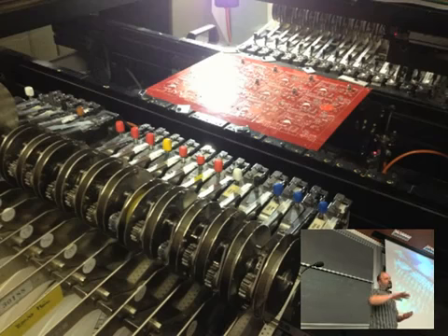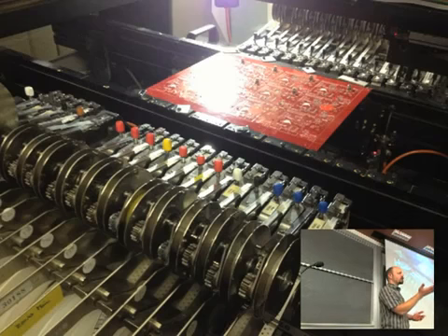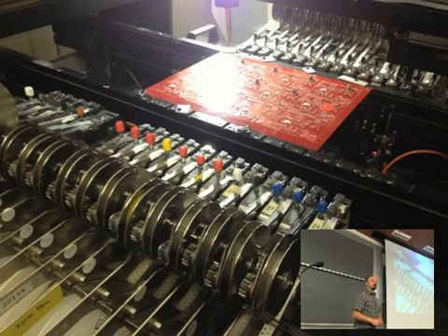Now, of course, if you have 2 layers, it's a whole different story. Because you put the parts on one side, right? If you put them through the oven, great, that will work. But how do you now put stuff on the bottom of your PCB? They actually do that at the same time, and how they do it is with glue. They first put a little bit of glue down, and then put the parts on top of it so the glue will hold them. Then they flip these boards around and stuff the second side, and then shove them through the oven that way. So that's how it works.